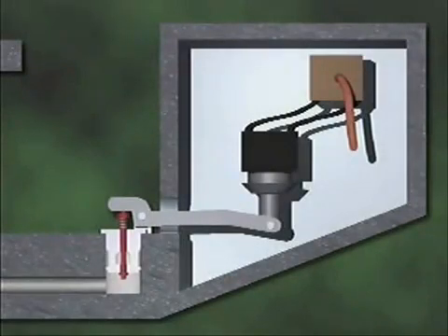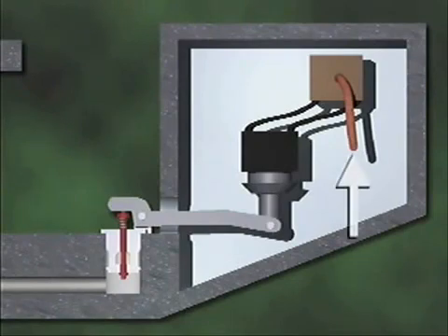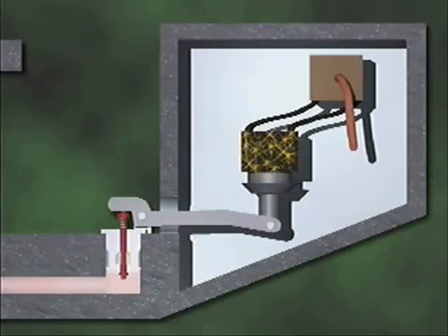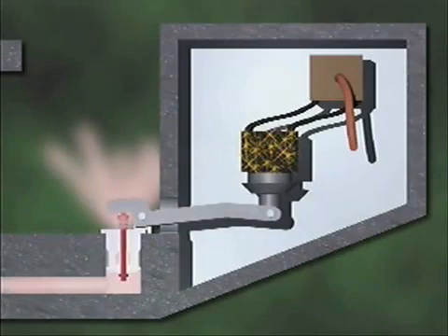The pilot device initiates the valve's opening. The device is set to open at a predetermined pressure. A pressure-sensing tube in the pilot device detects increases in system pressure, and when system pressure reaches the predetermined level, the pressure-sensing tube activates an electrical relay. The electrical relay closes an electrical circuit and energizes a solenoid. The solenoid then lifts a pilot valve, and the excess pressure is relieved.